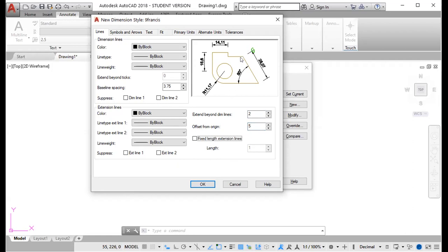You notice this changes. I'm going to change this to something else, probably 3, and press the tab key. What the tab key does is allow you to see the changes instantly. So this seems good. That is for line. We normally set up these 2 from line.